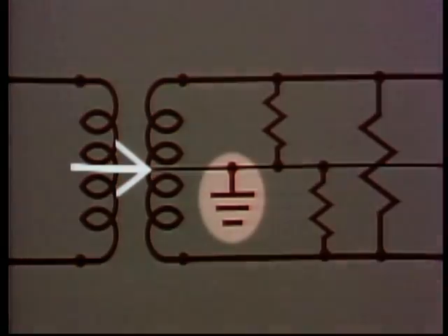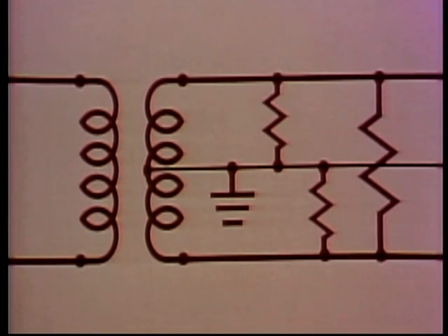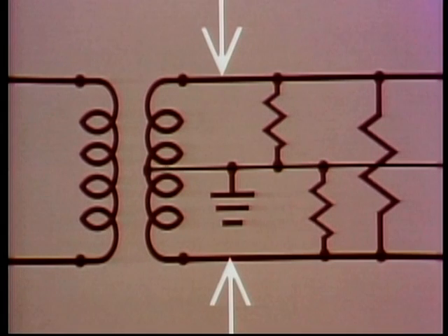In most systems, the neutral line is grounded as a protective measure. With the neutral line permanently grounded, if one of the other two lines accidentally becomes grounded, a short circuit will occur, and the circuit's fuses or circuit breakers will open the circuit. So, having the neutral line grounded allows you to know right away whenever a ground occurs. That's important because when you're connecting wires to lights and plugs, you don't want the top or bottom wire connected to ground, and you don't want the top and bottom wires connected together. Either of these connections would cause a short, and you could be shocked. By the way, one leg of a two-wire system is usually grounded for protective reasons too.